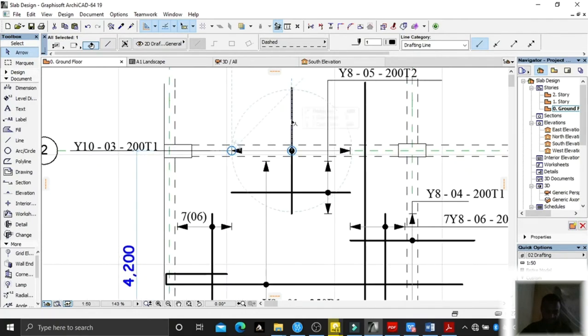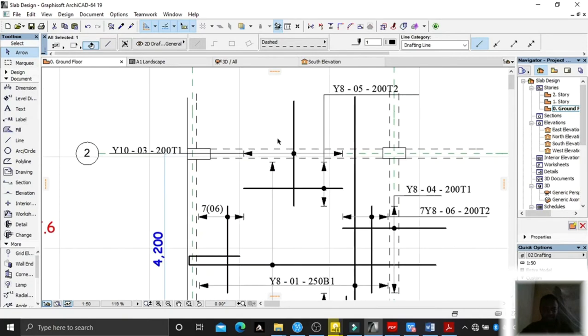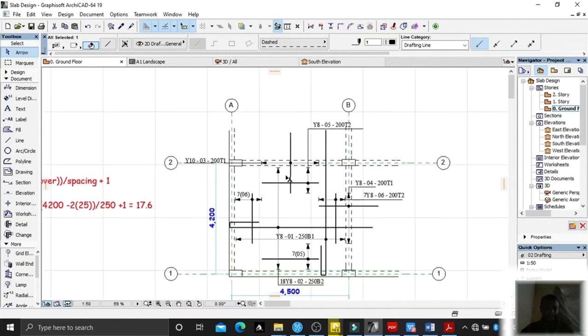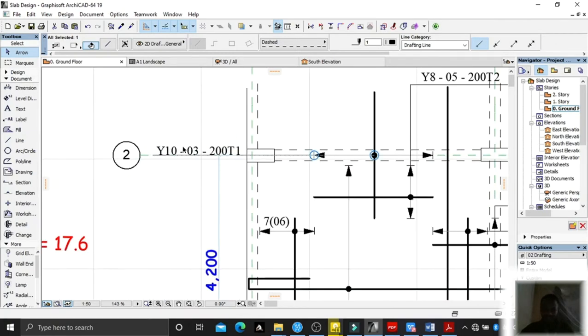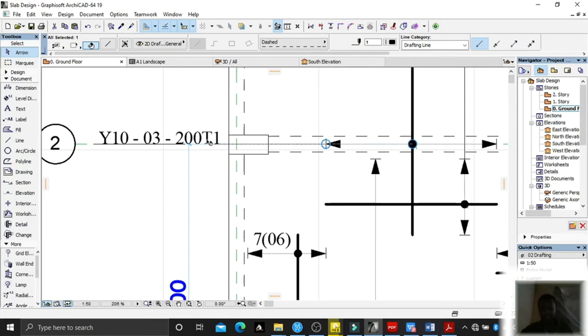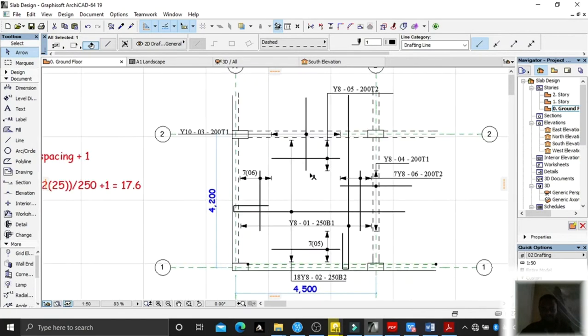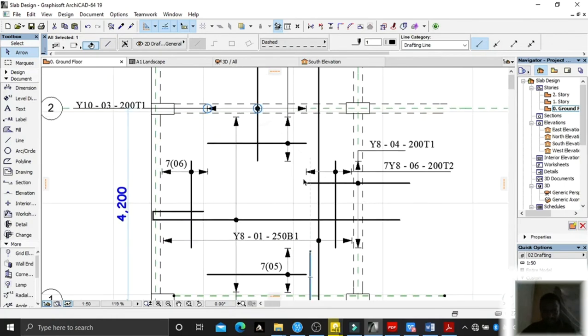For instance, this is a bar which is cutting through this beam, and the point where it ends is 25% to the edge of this beam, and again 25% to the edge of this beam. You leave that as a clearance actually. And we have these bars which are acting as top 1 being shown there. And as you can see again, the same labeling principle, but now we have them in T1, which is top 1. On this other end, our top 1 is actually represented by, again, the same way, slicing this beam.